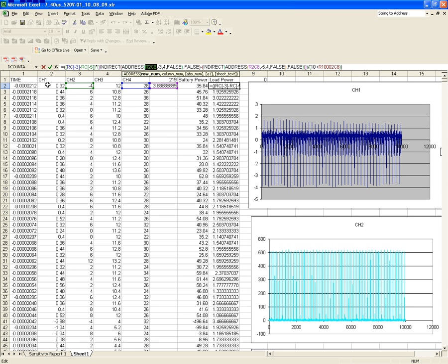And in order to determine that current, I have to take the voltage across the calculated impedance, which I want to be able to vary. So that's what this last part of this is. I have the 10 ohms of the resistance, which is a known calculated value or calibrated value, and then I have a reference to a cell where I add an arbitrary inductive impedance to see how that affects the outcome.